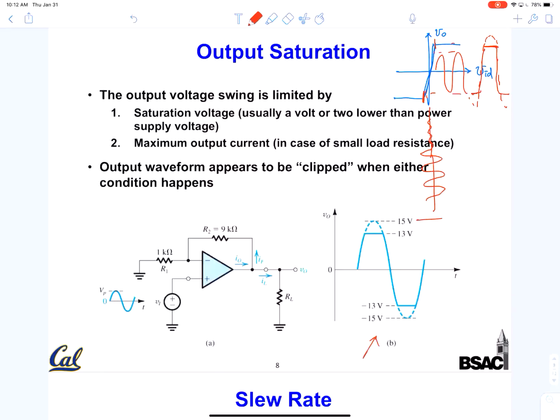Here, the 15 volt is the power supply voltage. You are not actually able to go exactly to 15 volts, as we see in the real amplifier circuit. The circuit will take a cut. There is some headroom, since your transistors still have some finite voltage drop across them. So you get very close, but not exactly.